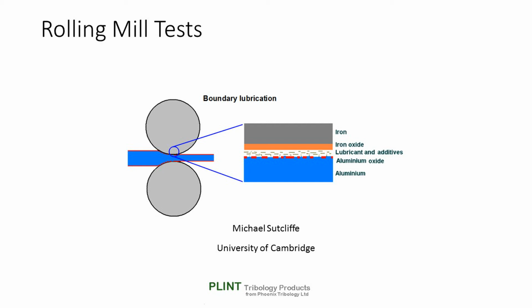Bulk strain elongation drastically affects the contact because of the way this allows asperity flattening. Long wavelength asperities tend to have smaller slopes and flatten more quickly. Multi-scale roughness has important implications for friction and roughness transfer, hence surface finish. Pitting can be an important consideration, in particular in rolling stainless steel.